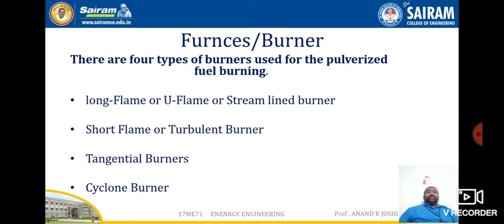These are devices that allow uniform mixing of the fuel and air, hence leading to efficient and complete combustion. The burner receives the fuel along with the primary air in a central passage, while in the secondary passage, secondary air is received. A good design of the burner is essential to achieve complete combustion of the fuel.